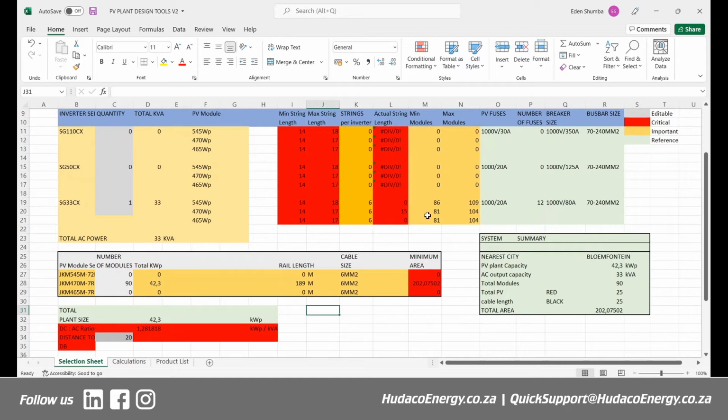Right, so it actually leads you to see certain limitations. To say, if I were to use 90 panels of this size, I'm going to get 42.3 kilowatts peak, but my AC to DC ratio is now in a range that is above that. Of which with the 33CX is not a big problem, because we said 33 kVA is just a nominal. It can go as far as 36. Okay, so you can do some further maths if you want to make it go as far as 35 or 36,